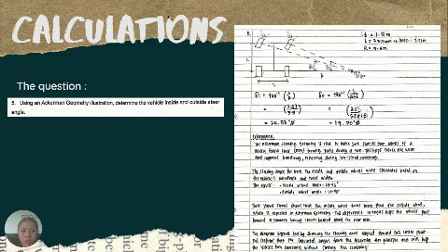outside steer, then inverse tangent multiplied by L divided by R, and got the answer 24.53 degree for the inside steer, and for the outside steer I got the answer 19.70 degree.